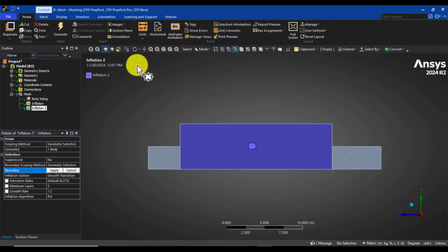Now, as I draw a box by drag and dropping the mouse, all of the sides inside this box would be selected. So all I have to do is to draw a box in this region where the car is located. Now you can see that all the faces are selected, and I can apply that. By now you can see that 175 faces are included for the car.